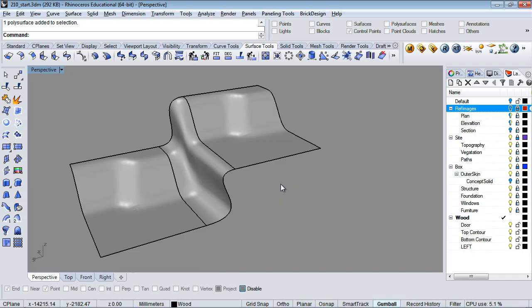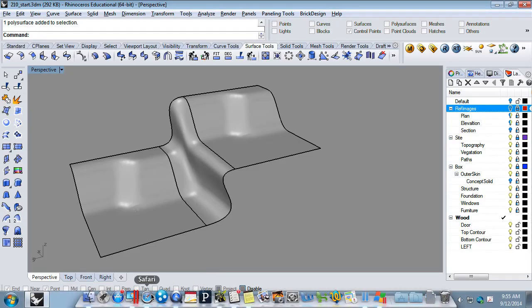So that's what I want you guys to work on. Work on the C-planes, building out those profiles, sweeping into sections, and maybe work in smaller pieces, but think about how you would break up this surface so that you could use this blend tool to make it easier for you to build up that surface in chunks. Okay? All right, so that's it, and just get to work for the rest of the session.